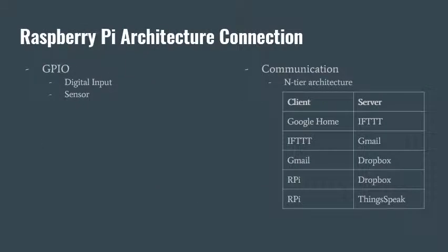The most significant input of Raspberry Pi in this project is the temperature and humidity sensor that was connected through GPIO. GPIO is a physical interface that takes only digital inputs, high voltage or low voltage, corresponding to 1 or 0, and since it is programmable, the data can be read and translated to useful information.